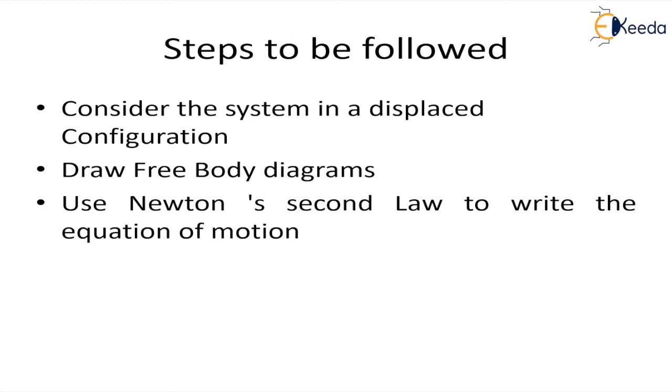So it doesn't matter what system we are studying or how many degrees of freedom we have. The simple steps to follow are to consider the system in a displaced configuration, draw the free body diagrams, and apply Newton's second law to write the equations of motion. Once the equations are there, we can easily solve them and do whatever analysis we want.